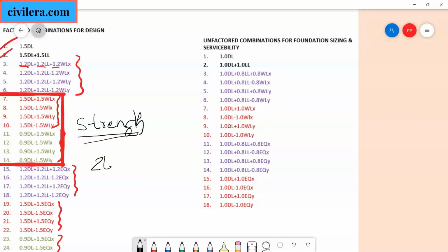we are not factoring it, because when you check deflection, even when earthquake or wind occurs and the building laterally sways, we are not considering a factor of safety there, because already we are considering a huge amount of load, and it's not a threat to the collapse of the building. The deflections only create a kind of discomfort and also maybe minor cracks and things like that. So for serviceability check, we don't need to factor the load.